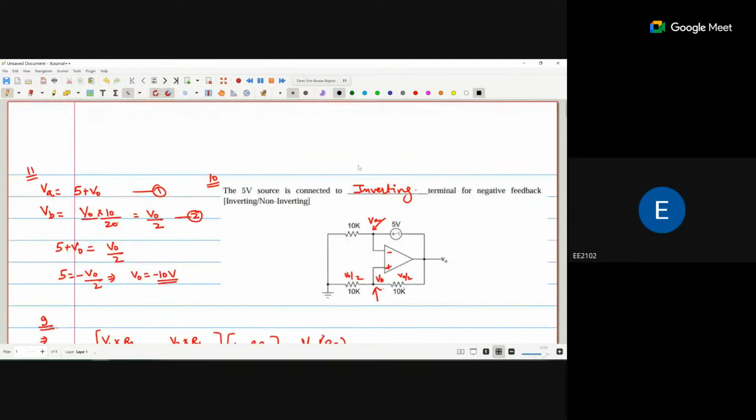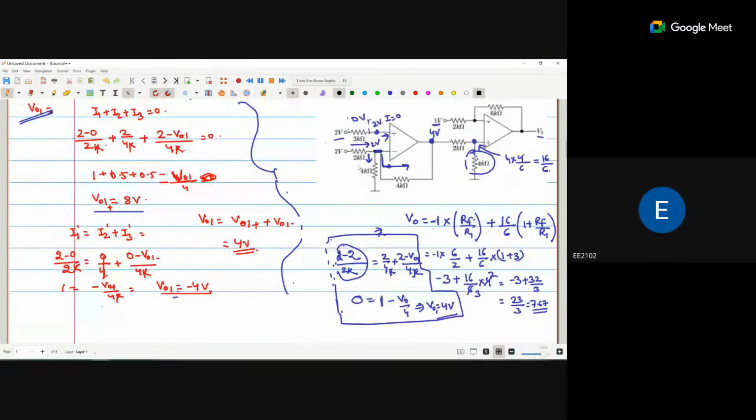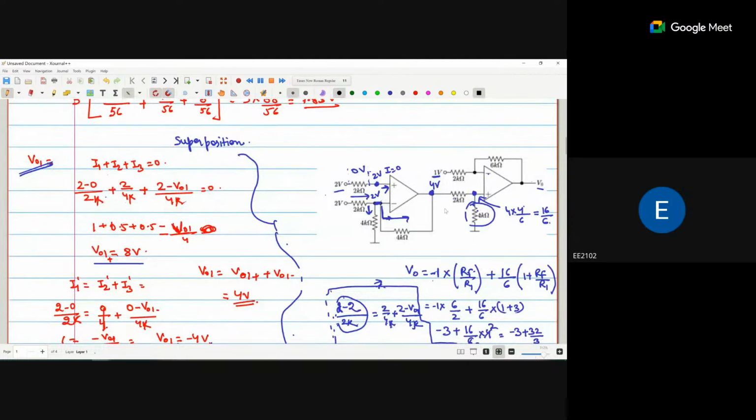In this question we have two operational amplifiers. Output of one operational amplifier will connect to the other input. In between them, if we use a capacitor, that capacitor is used for the coupling part. One output will be coupled with the other input. So that's why it is called the coupling capacitor. Generally, we use capacitors for two purposes. One is coupling, one is bypass.